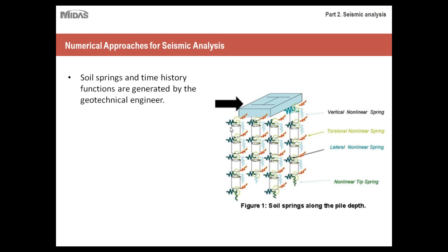For example, just imagine a bed spring pushed up against a cinder block or a tube. If you were to apply a force to it, that spring would oscillate. Just try to imagine it that way. That's why they're called springs. These spring elements take into account the oscillating behavior of, say, a pile foundation when you apply a seismic load to it; it's going to shake back and forth. These soil springs would take into account that type of behavior.